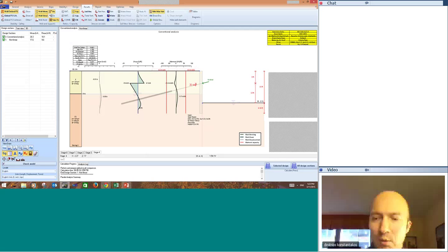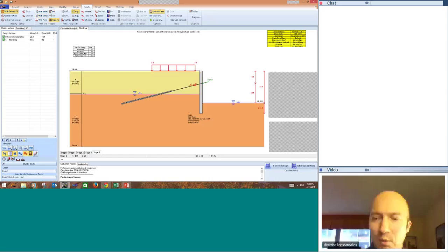An important thing to check on our wall embedment safety factors is that our hydraulic heave safety factor stays above 1.5. That's a general recommendation. But now what happens is that our support reactions have gone down, our wall displacements have gone down since we've assumed wall friction, and our required wall embedment has also gone down to 7 feet. Now, my general feeling is still that I would specify at least 10 foot of wall embedment because sometimes there can be over excavations and so on. But theoretically, at 7 feet, you will be fine.